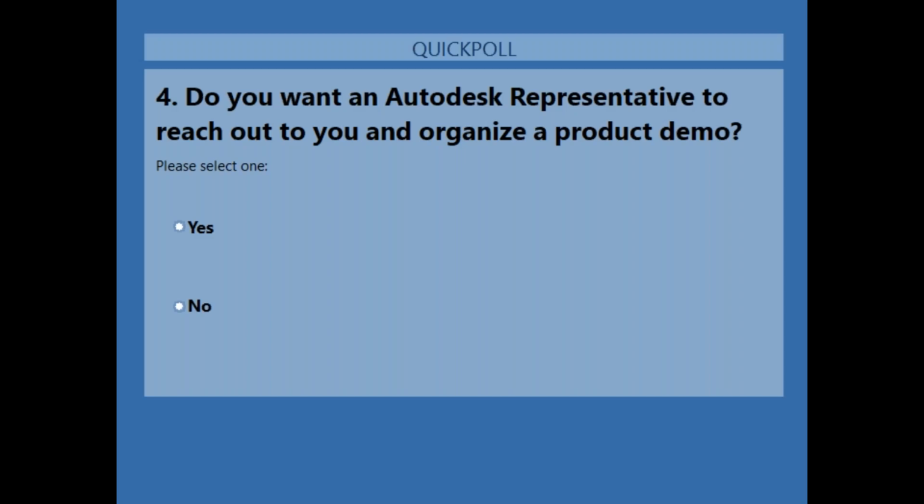Coarse mode will just give it a line. While working, I also recommend working in a scope box or a smaller area which you are detailing, so that the view is much faster and easier to handle. Rebar on a linked file is not recommended; it is mostly better to do it on the main file.